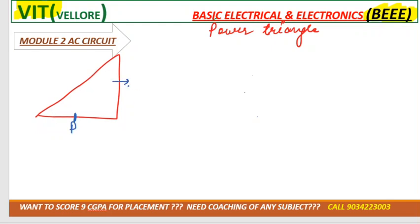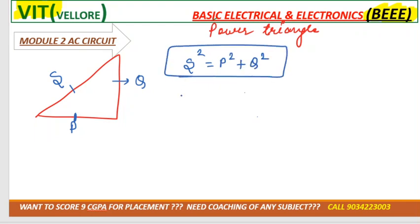P. And which power is consumed by inductive and capacitive load? That is the reactive power, and the combination is known as apparent power. Okay, understood? Okay, so we'll have S square is equal to P square plus Q square, right? And can you tell me what is cos phi in this case?